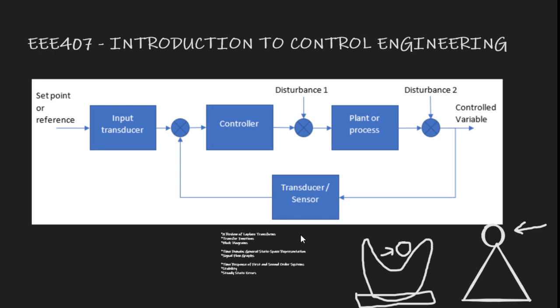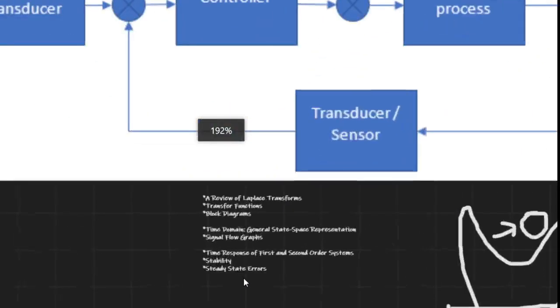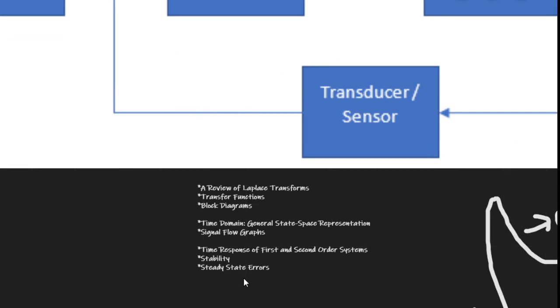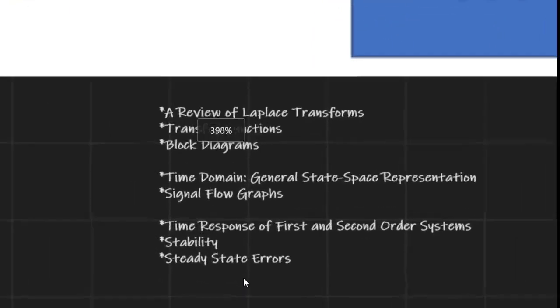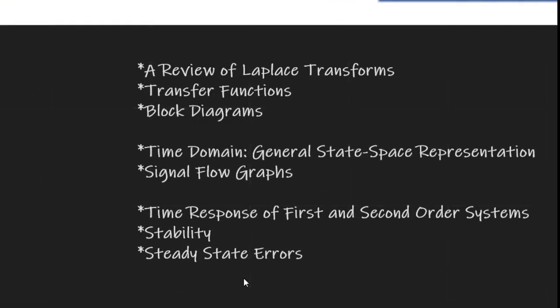So we've talked about time response. How will the system behave over time? We've talked about stability. In the end, will the output settle to something, or will the output just keep on growing without bounds? Then the third thing we talk about is steady state error. In other words, let's say I specify that I want this thing to go to so and so position. When it settles, let's assume the system is stable and it settles somewhere. Does it settle where I want it to?